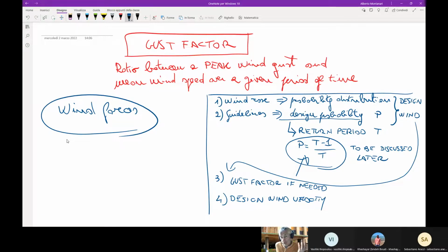This is a second issue that is important. Another issue that is important to understand is whether or not the ship tends to rotate. If the ship is just pressed against the berth or pulled from the berth on the seaside with no rotation, it is a better situation with respect to some pull plus rotation. Let's try to have a look at these details.